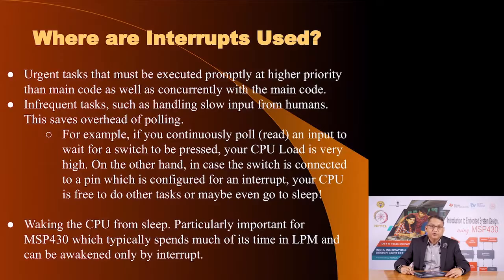Now, where are interrupts used? Well, typically when you have an urgent task: you are performing a main program and some urgent task comes, you would like to deal with it by suspending your existing program, dealing with this urgent task and coming back to continue the ongoing program.